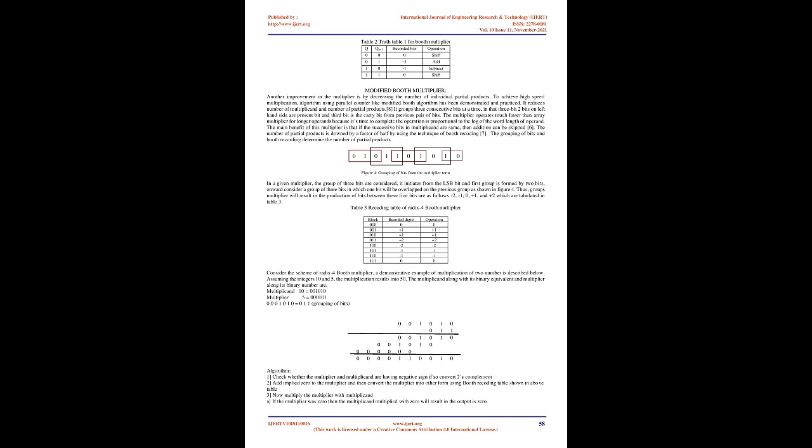Each multiplier bit generates one multiple of the multiplicand that should be added to the partial product. In this case, the delay of the multiplier is mainly governed by the number of additions to be performed. If there is a way to reduce the number of additions, the performance will be better. It is the standard technique used in chip design and provides significant improvement over the long multiplication.